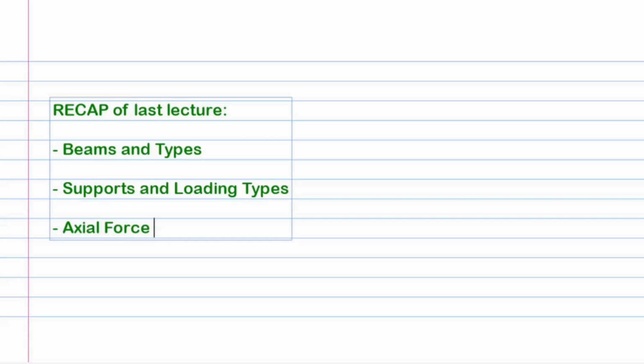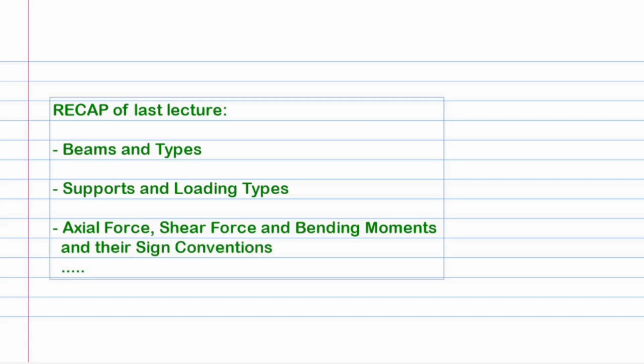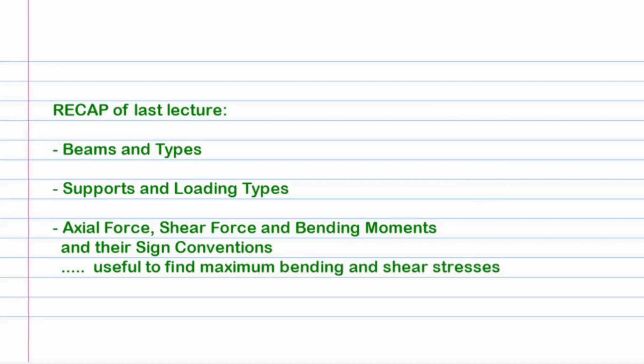along the beam's length, which are called the axial force, shear force, and bending moment respectively, together with their sign conventions. These shall further be useful to calculate the maximum induced bending and shear stresses at a later stage.